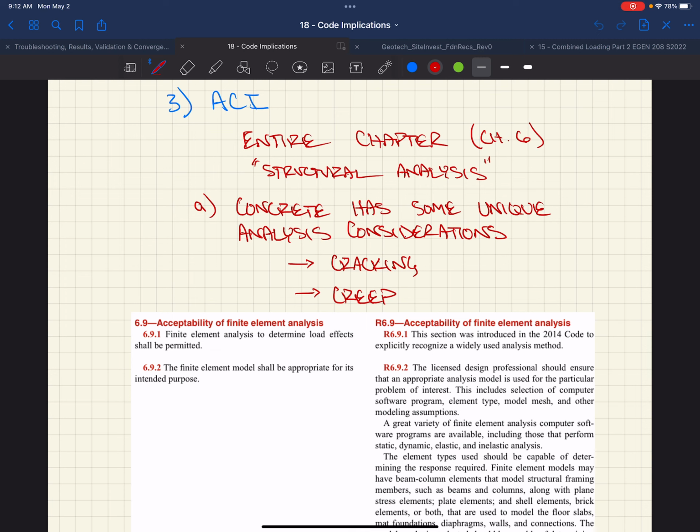You guys have all seen the edges of Cobleigh Hall, right? The corners that are creeping down. Go out, turn around, and look back: two corners that are cantilevered are falling. If you go up to the transportation lab, they have those big angles on the floor. That was an effort to minimize the droop of the corners, right? And they also re-bricked those corners because they were starting to come apart. They've deflected that much.